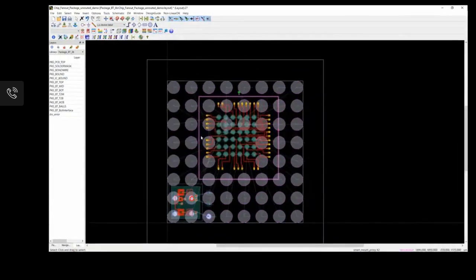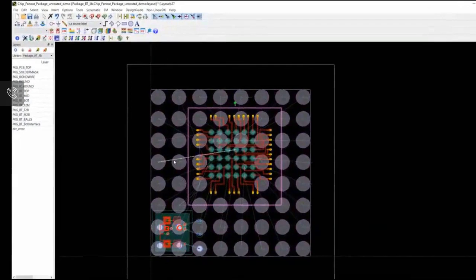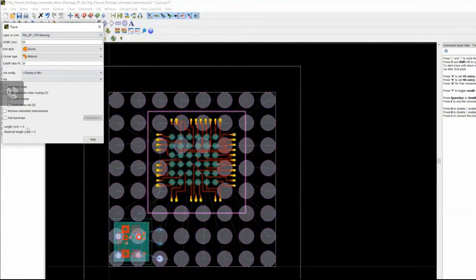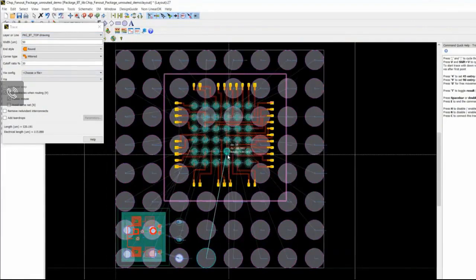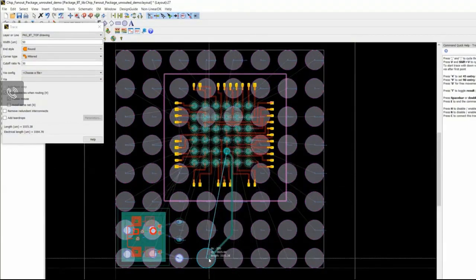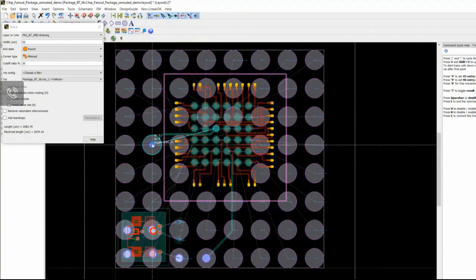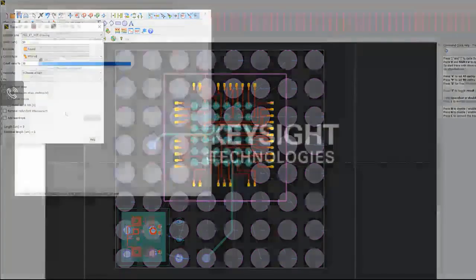The flight lines you see here will help guide me on where the interconnects must go in order to match with the schematic. So now I will use trace routing in order to perform the connections. Notice the routing also has automatic collision avoidance. This prevents lines on the same layer from colliding or shorting and also helps avoid breaking any DRC rules.